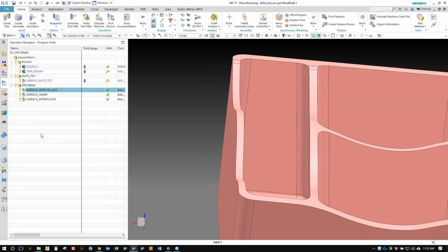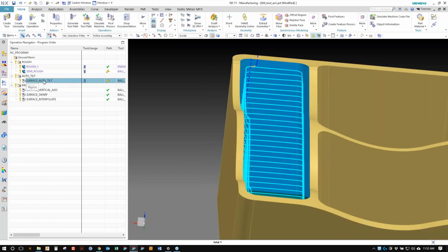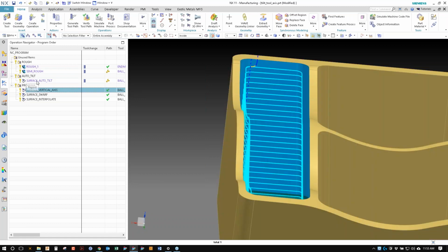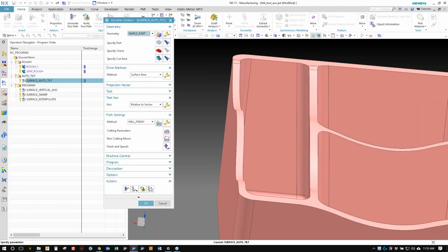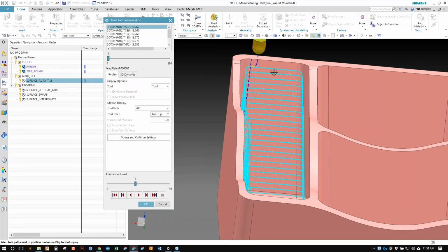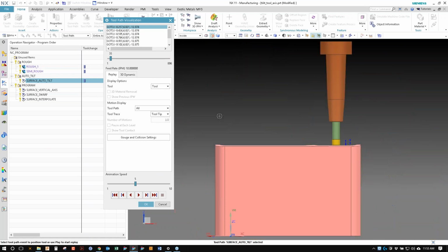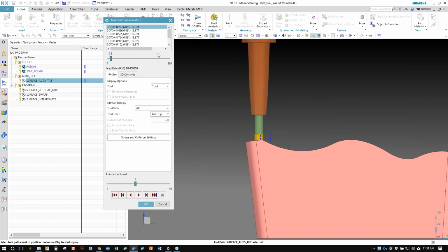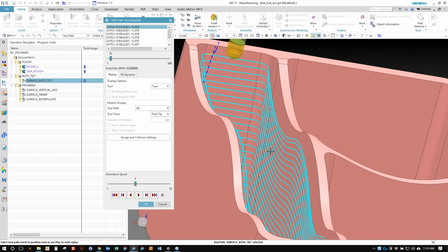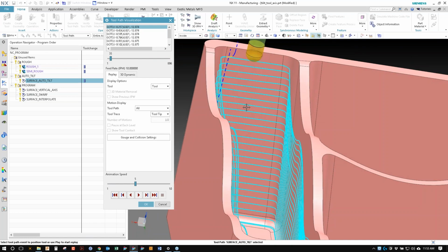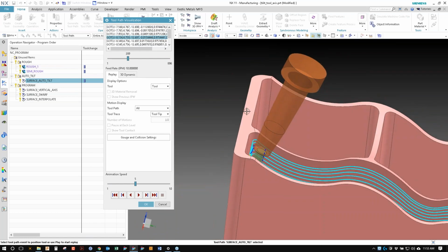What I like about using a vertical toolpath that's not already tilted is that it'll start at the top with a vertical toolpath. I'll show you that before we process it. This toolpath here has already been tilted, and I'll walk you through the steps of how to do that. But just to show quickly, at the top of the toolpath, if I look at this normal, it's vertical, and then as it gets into an area that would collide, if I click down here further, it starts to tilt.